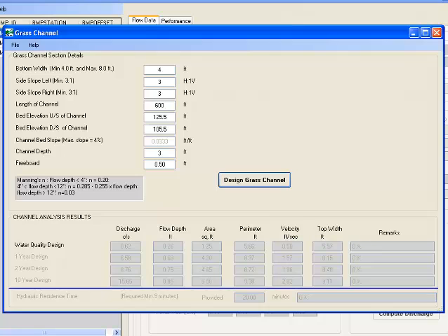You will notice that the second column of the bottom section, giving the water quality design discharge and the 1-year, 2-year and 10-year design discharges, is already populated. The bottom width varies from 4 to 8 feet. Channel side slopes should not be less than 3 horizontal to 1 vertical. The longitudinal slope of the channel should preferably be less than 2%, but be no greater than 4%. Check dams can be used to reduce the effective slope for meeting limiting velocity requirements.